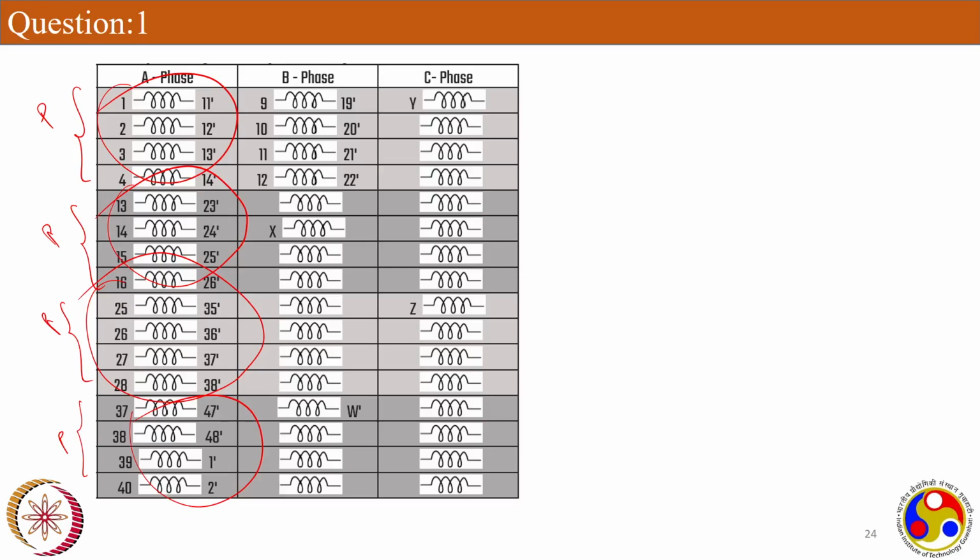The EMF per coil group would be 107, and you just have to multiply it by 6, the number of poles. This is one example that will make our understanding easy. For each pole, we have a single coil group, so based on the number of poles you will have that many coil groups.